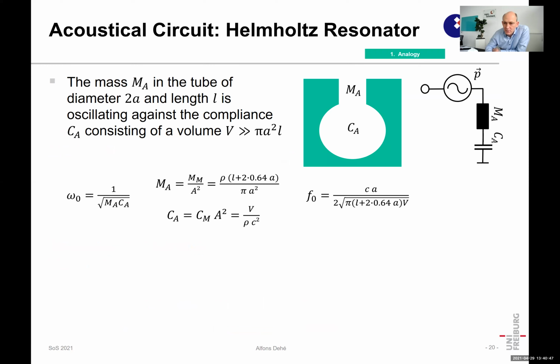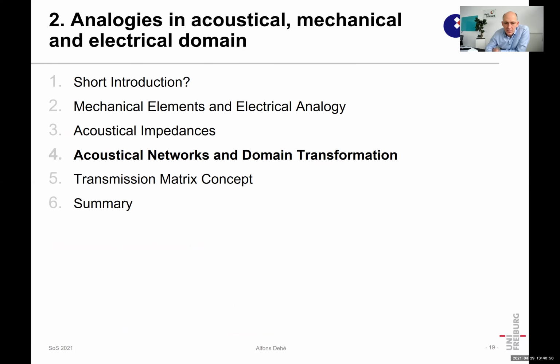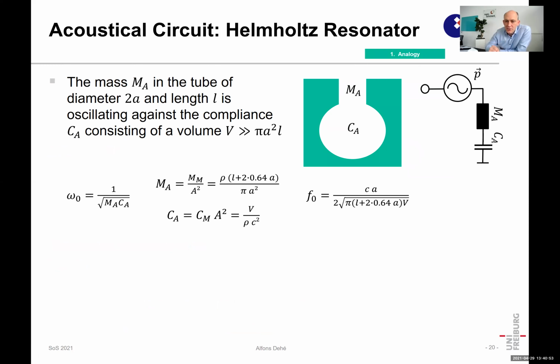Okay, I will give you some example about an acoustical circuit. A very, very simple one: usually people know the Helmholtz resonator, which can be a bottle with a flange and a volume behind. So this is the bottle situation. If you have air streaming along this, the mass in the flange is getting accelerated, getting into resonance maybe. Everybody knows that's generating tones, and the mass is accelerated or vibrating against this volume inside. This is our acoustical compliance.